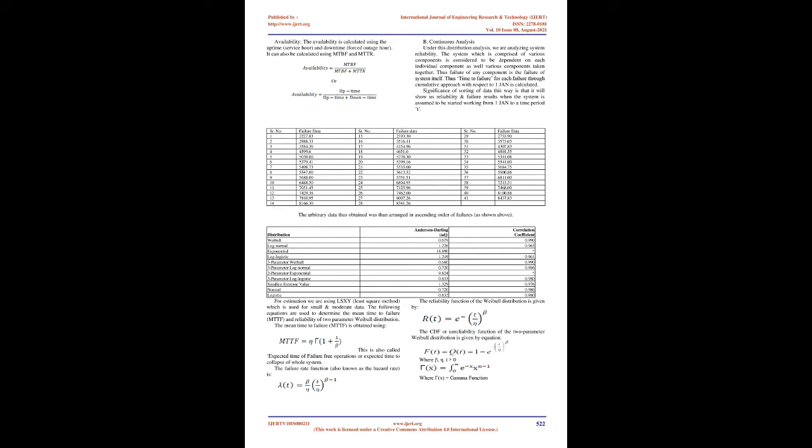One of the most used common life distributions in reliability analysis is the Weibull distribution. The 2-parameter Weibull and 3-parameter Weibull differ only by the location parameter, which has just the significance of shifting the origin. Weibull can be easily applied to a large number of situations and small data sets. It can also be used to model both increasing and decreasing failure rates. The main advantage of it is its ability to handle small samples and its flexibility to fit different failure modes.